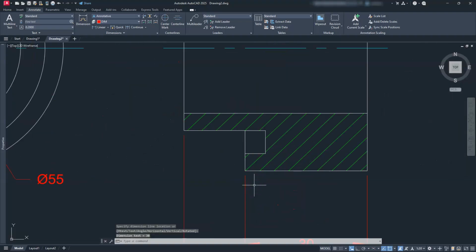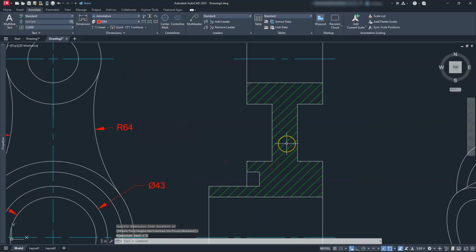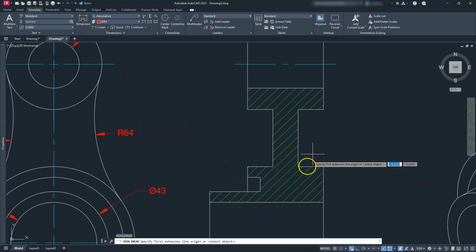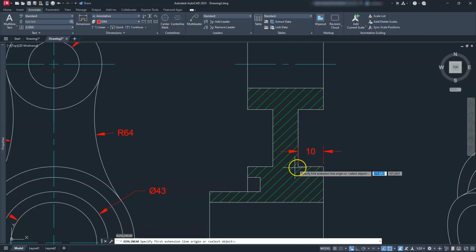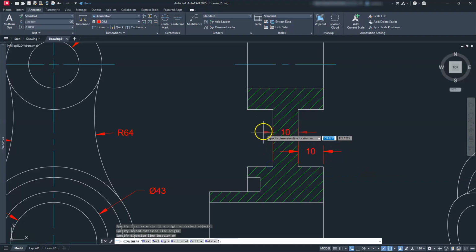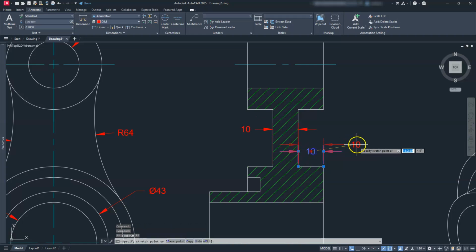And make sure you're understanding how I'm selecting these. I want my number on this 5 to be on this side, so therefore I'm going to select that endpoint first, and then here, and then it's going to kick it out going that direction, right? So work here on the top one here, so I'm just going to hit enter from here to here. So hold it there, hit enter again. So from here to here, go ahead and click it here. It puts it on the inside. Let me escape out of that. I'm going to select this dimension here. I'm going to go and find that middle grip, and I usually like to pull these to the outside. Same with this one here. I usually like to keep these kind of going to the outside so there's no confusion.